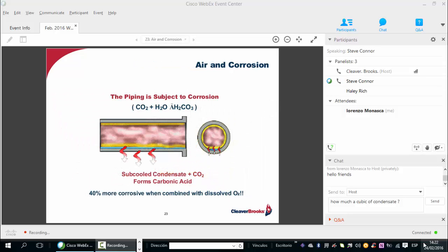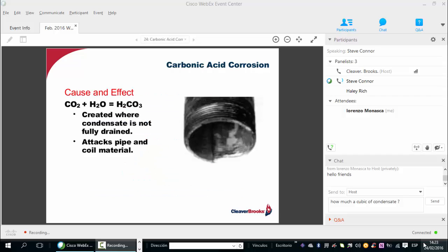dioxide. And speaking of carbon dioxide, it initially comes into the boiler through the feed water supply as carbonates of alkalinity, carbonate salts, and resides as part of the boiler's TDS. The problem is, when the water evaporates, steam is formed, and goes out to do its work and then condenses, CO2 is formed, combines with the cooler condensate water in the piping, and becomes carbonic acid, H2CO3, which will attack the condensate return lines. And if oxygen is present as well, it becomes even more aggressive.